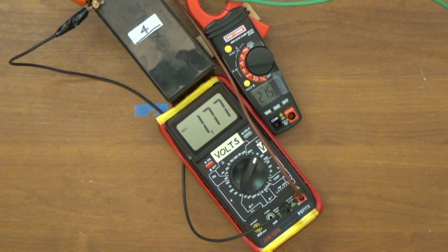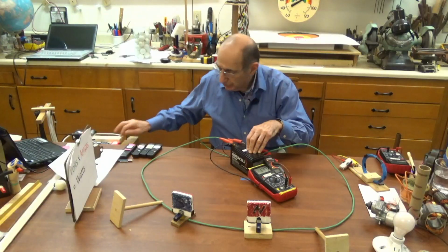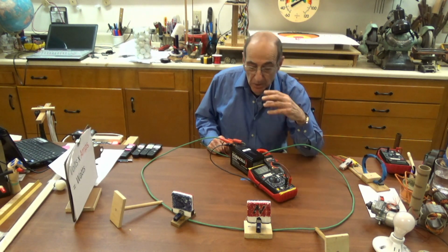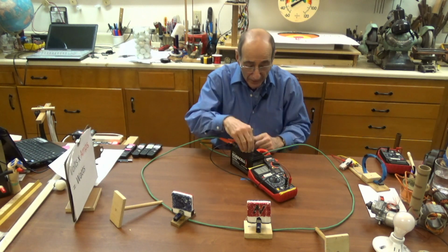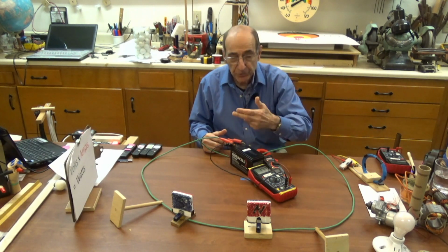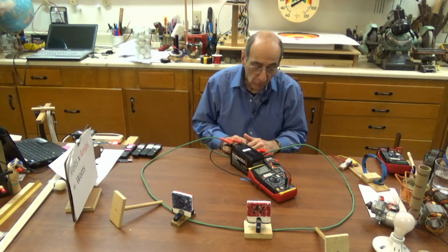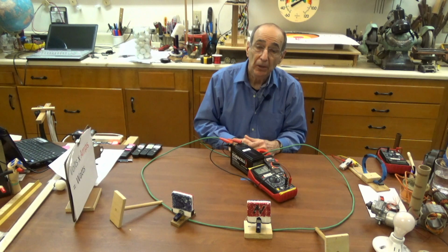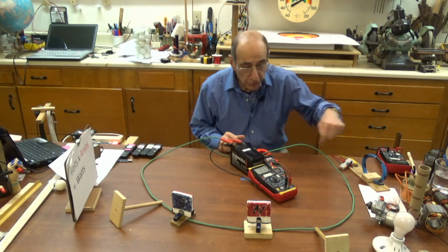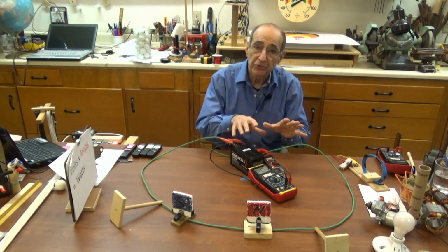Why did the voltage drop? Well, all sources of electricity have resistance. And so the device itself, like the battery, although it's producing the voltage, if we try to flow too much amperage through it, it uses up its own voltage. And in this case, it used almost over 10 volts of what it's putting out chemically, because we were sending too many electrons through the battery. But that's okay. Our experiment is going to be just fine.